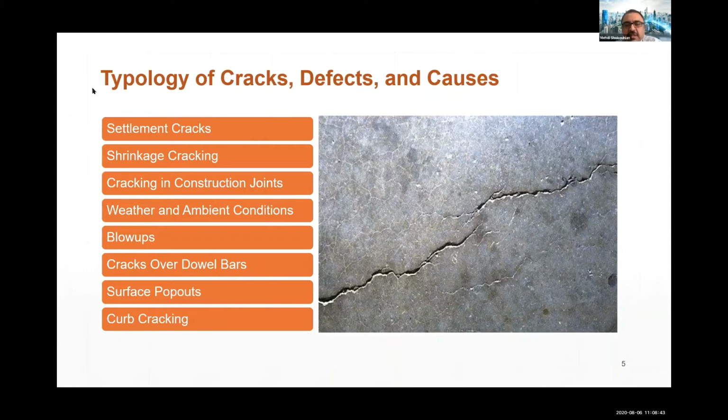The similar concerns that we have in terms of the defects and causes of these defects for rigid pavements can be applied to bus pads. In addition, there is the type of load: more frequent and repeated load over time, and the fatigue load needs to be taken more seriously than for rigid pavements.